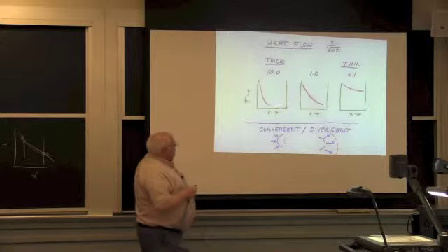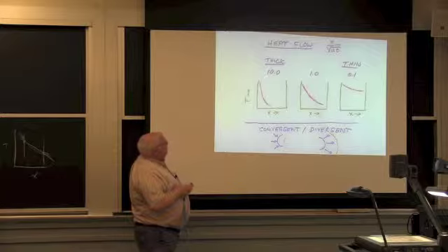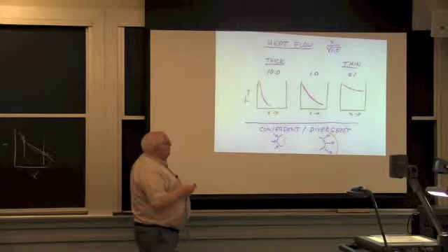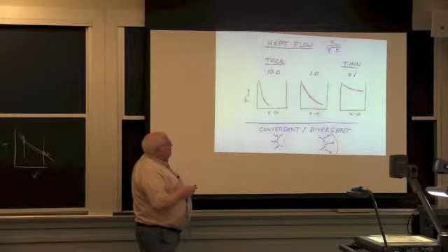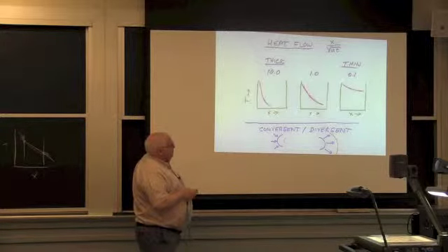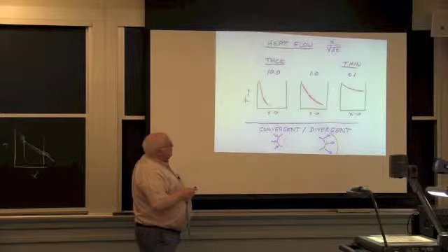Okay? If you are infinitely thick, it turns out for a Fourier number of 1, you're basically in this situation where the distance the heat travels divided by the speed at which it travels, if you will, is a similar ratio. And so if these are the boundaries of my system, one edge here and one edge here, and the heat is flowing through here, heat is starting to go from one surface and start to accumulate on the other surface if I'm near a Fourier number of 1.